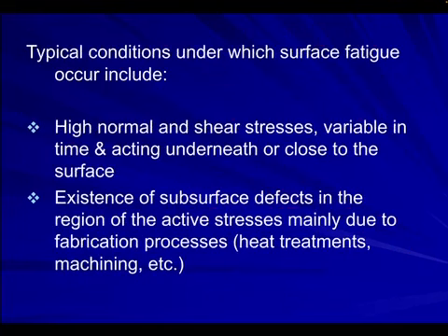So typical conditions under which surface fatigue occurs are high normal and shear stresses, variable in time and acting underneath or close to the surface. Existence of subsurface defects. So, of course, this is a fatigue type of mechanism, and so a defect will give that initiation point for the crack to start. So that's in the region of active stresses, mainly due to fabrication processes, maybe through heat treatment or machining, etc.